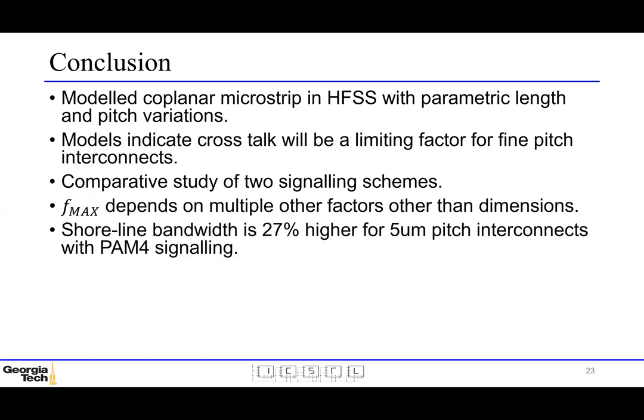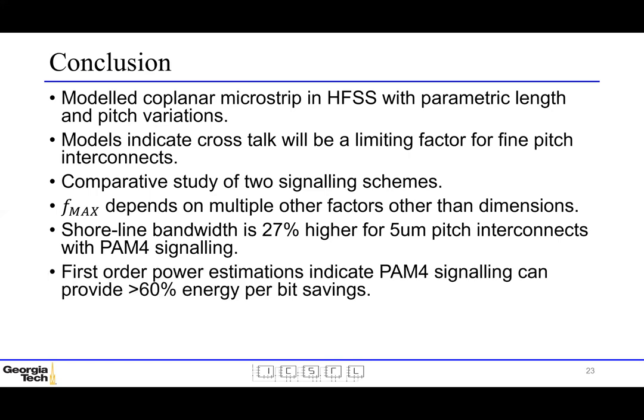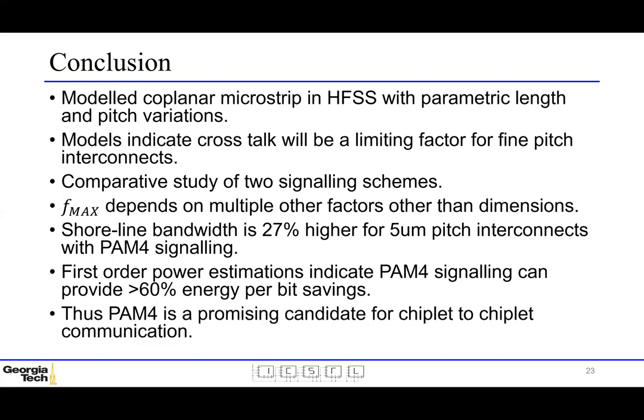The shoreline bandwidth density, which is defined as the bandwidth per unit length, is 27% higher for PAM4 for 5 micron pitch. The first order power estimates show that PAM4 is 63% more energy efficient in terms of energy per bit transmitted. Thus, we have systematically demonstrated through this model study that higher order modulation schemes like PAM4 are promising candidates for short length, fine pitch, chiplet to chiplet interconnects.